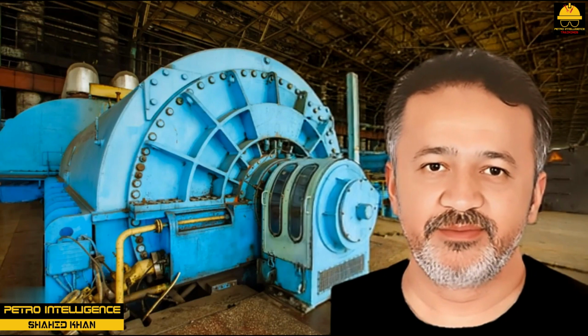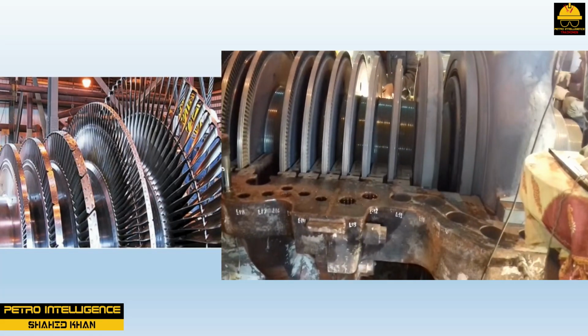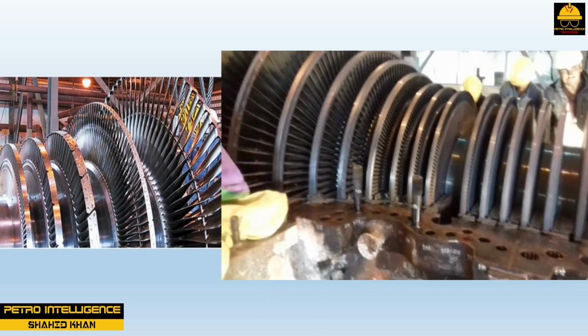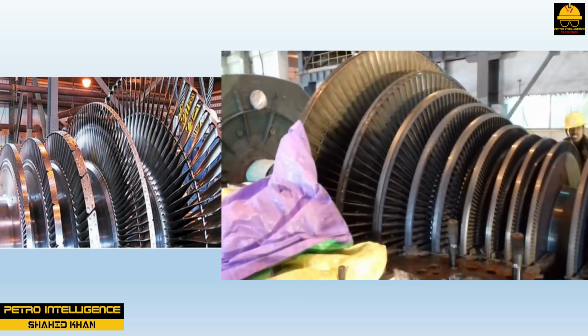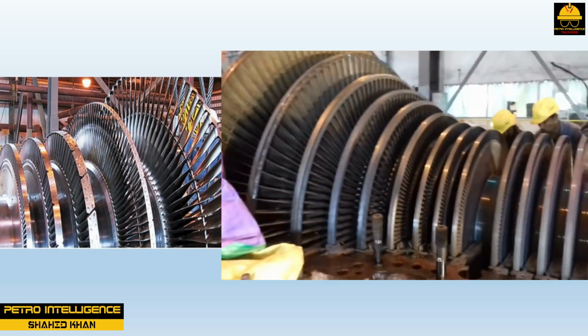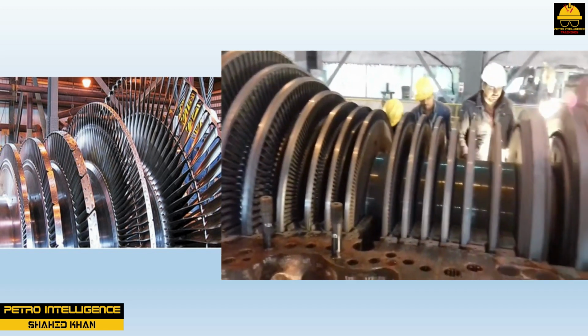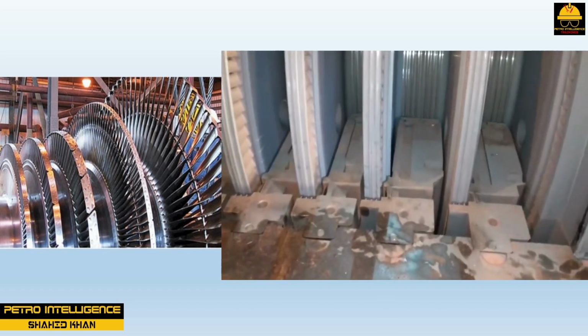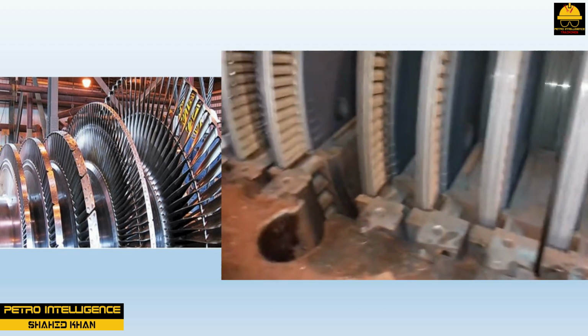Fixed blades. The fixed blades, as shown in the picture, are made of durable stainless steel that has been rolled and drawn. The fixed blades are a half-moon shaped ring located in the lower section of the turbine, sandwiched between the moving blades. When fixed and rotating blades are aligned in the correct position, steam passages are formed across the wheel of the turbine.